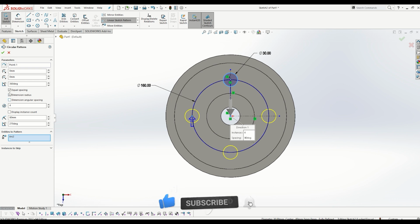Another box is dimension radius. If you don't already have the pitch circle diameter as a reference, without a reference also we can create the pattern. In that case you have to fix that distance, so that's why we are using the dimension radius. I will show you. Already I have checked that dimension radius box, and this one is dimension angular spacing, which is nothing but not equal spacing.